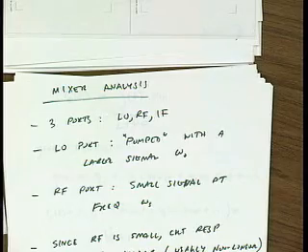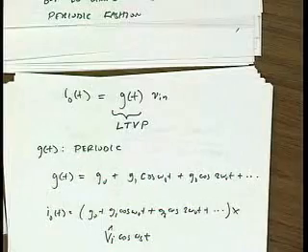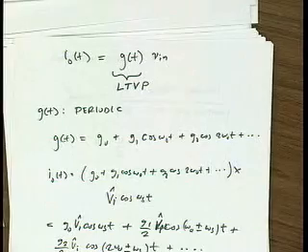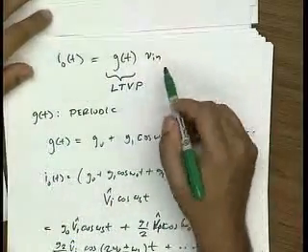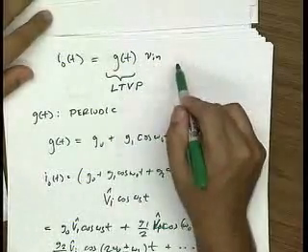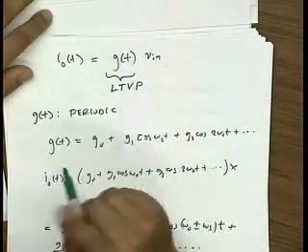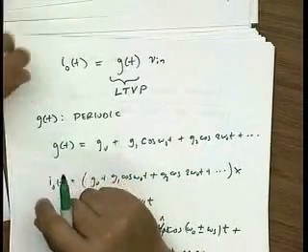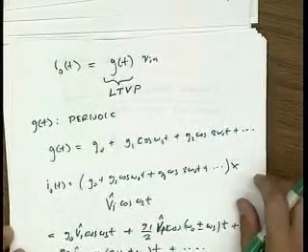Earlier, in the expression you have, I can see the time-variant essence in here, but I think the same equation would apply to the nonlinear system. No. Okay, so if we wanted to include nonlinearity, then the output should not see a linear function of the input voltage, but it should see a Taylor series expansion, where the Taylor series coefficients would be a function of time. We'll do that in the next lecture, actually. So be patient. Let's take things one step at a time. All right. Make sense?